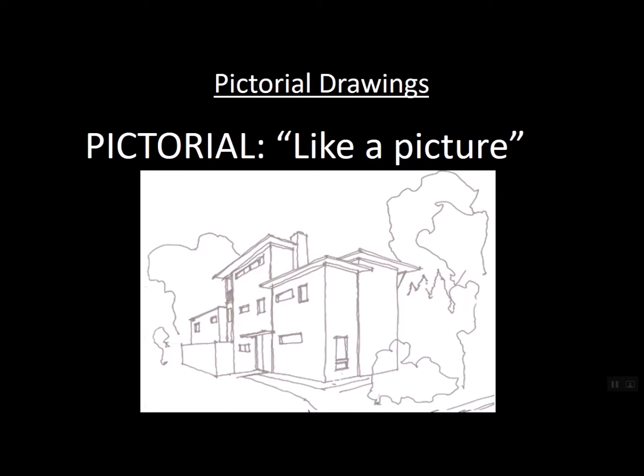So this is considered a pictorial. It's not a flat orthographic drawing. It's a what do I see observing it. And in orthographic drawing, remember there was the front and the right side and the top view. Well, in a pictorial view, you will see at least two of them, maybe all three of them, depending on the angle that you're looking at. So we're kind of switching gears from making things flat and unrealistic, but the correct size and shape for fabrication, to what does it look like.